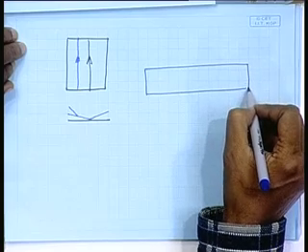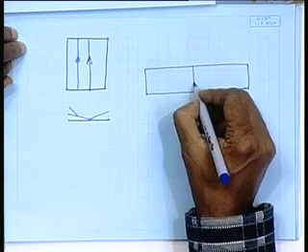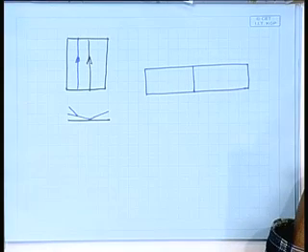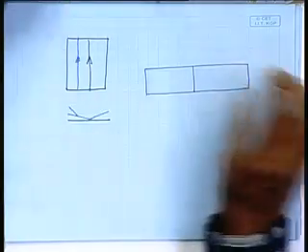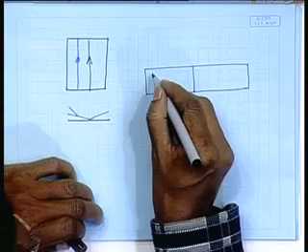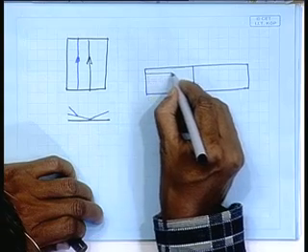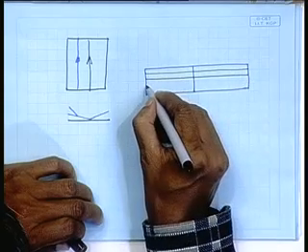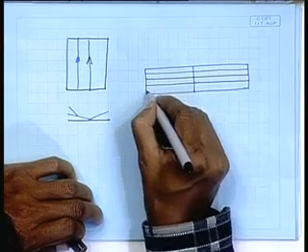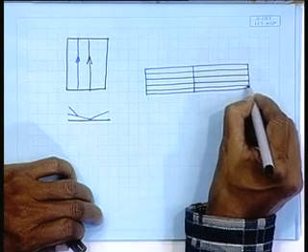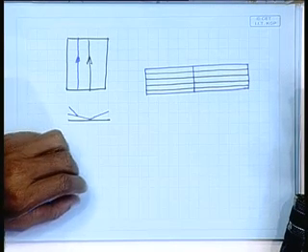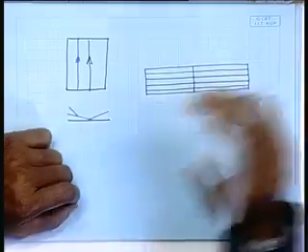I am drawing it a little thicker. Along the thickness there is a temperature gradient. If it is there, let us assume that the plate is made up of various thin layers, or in other words, we discretize the plate thickness into several thin layers, and we said that if the plate was thin, I could have attained the same temperature both at the surface and the bottom.